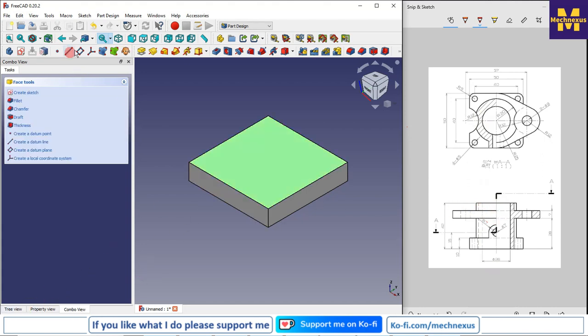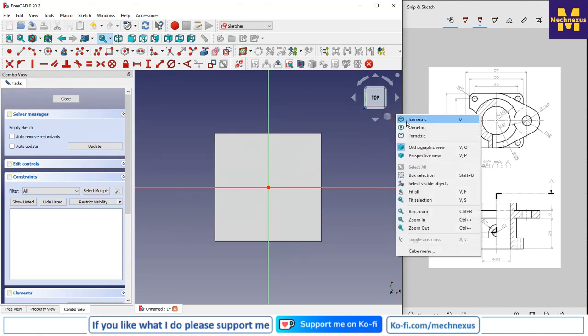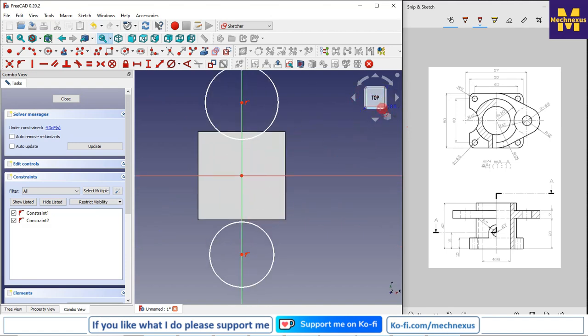I will select the face and create a sketch, and I will switch to the isometric view. I will draw two circles on both sides, and the center to center distance is 57. First I will make it symmetric. I will select the first center point, the second center point, and this axis.